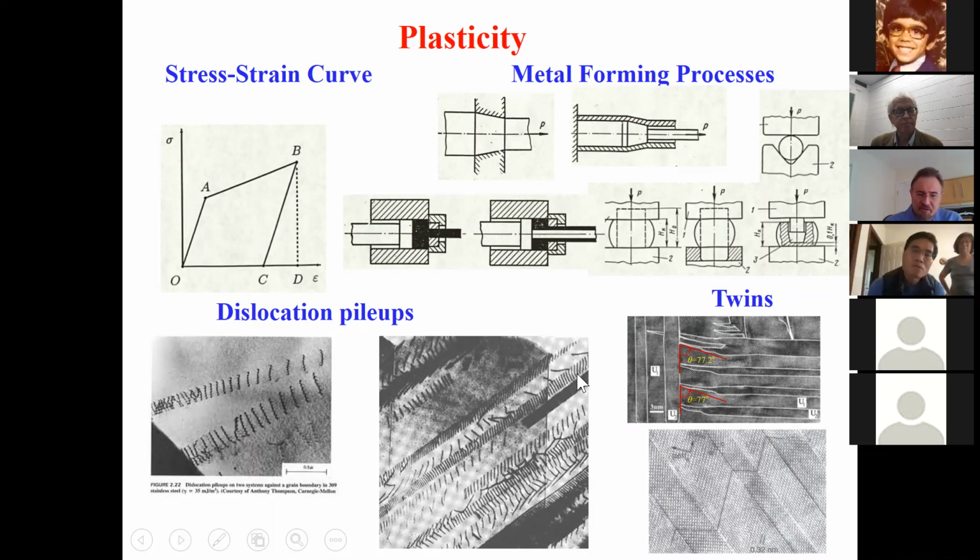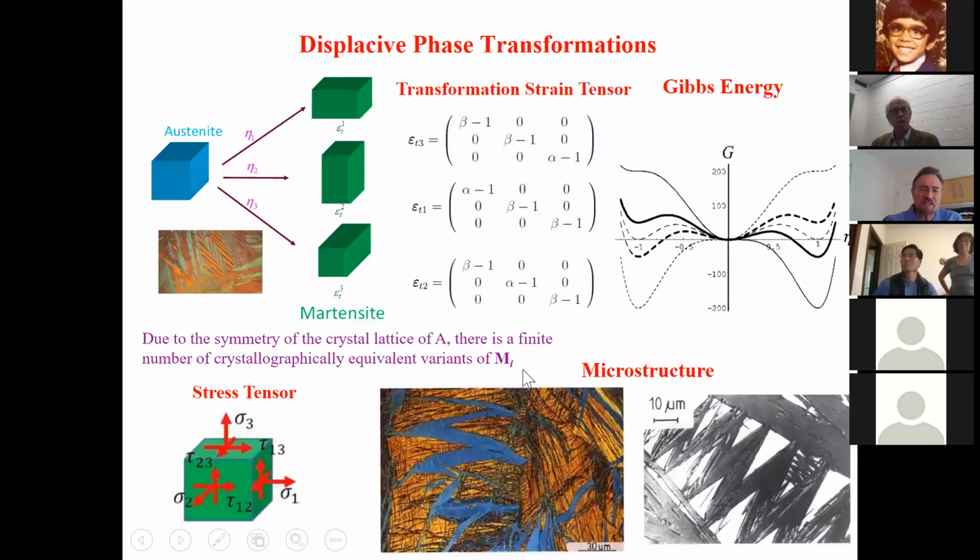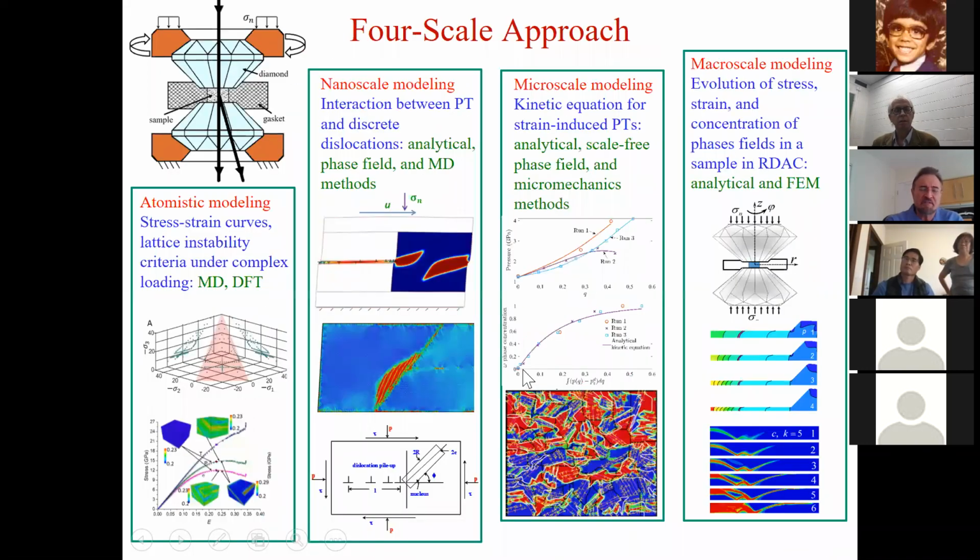Here it's even longer, I don't know the scale here. So it can be at any scale, but mostly in our case, I believe this is at nanoscale. Why? Because after large plastic deformation, we obtain nanograin structure. So the dislocation pile-up should be like 100 nanometers, 50 nanometers.